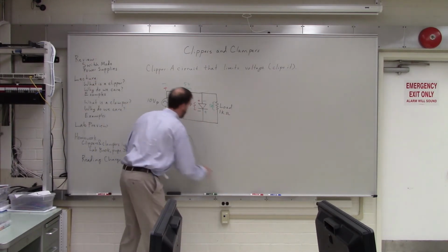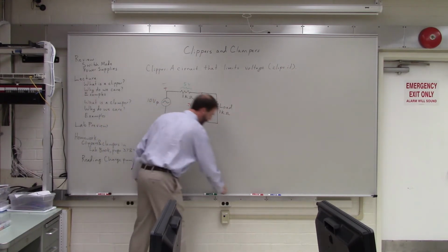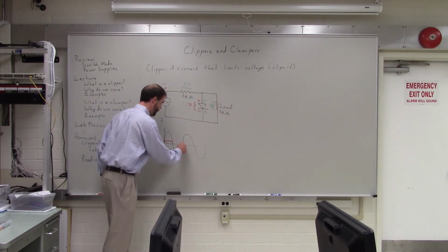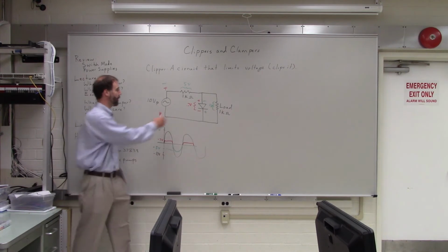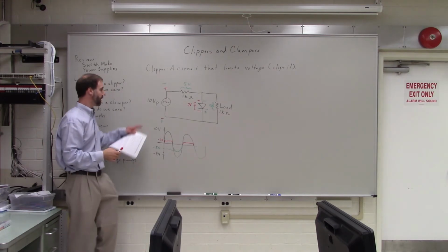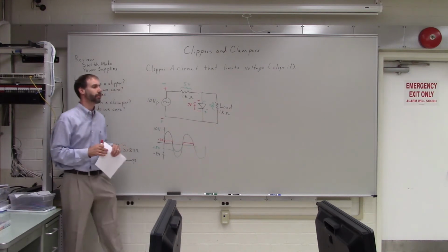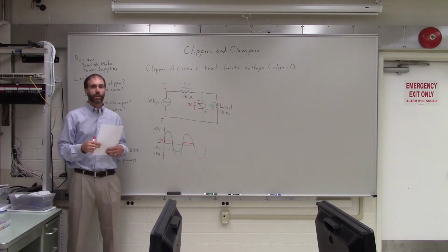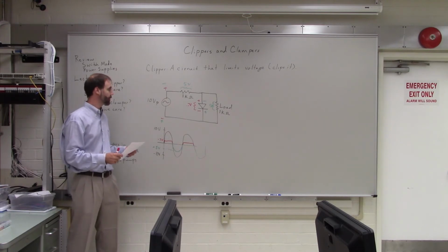Okay. So, and then this repeats, right? Every time. Seems like even the resistor kind of works as a filter. Well, sort of. I mean, you can't call this good, right? It reduces the signal, but it doesn't limit it at a particular voltage. This one always cuts it off at 0.7 volts, no matter what your input voltage was. So the clipper circuit always cuts it off at a particular voltage. Does that make sense? Yes. Okay, so that's one example of a clipper circuit.